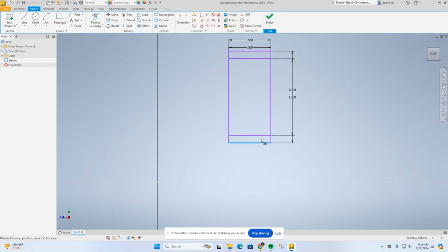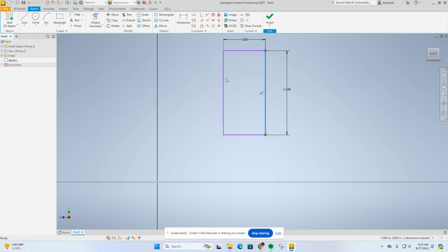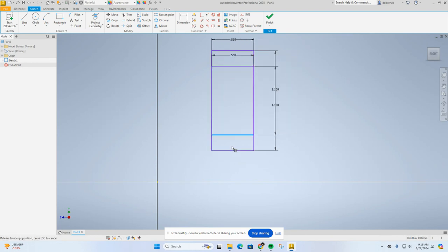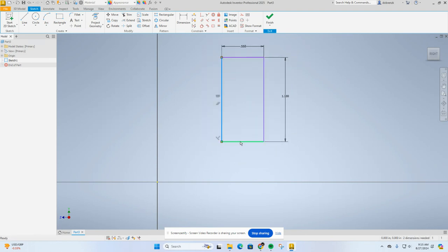What it's telling me is, I see this rectangle. You can move it around because I don't know where it's supposed to be, where it's supposed to end up, where it's supposed to live. So what I have to do is use dimensions to tell it. I could also use constraints, but right now we're talking about dimensions. So per that sheet, there was a dimension that went from this dot to this line. And if you see here, I have my same arrows and it only moves up and down.